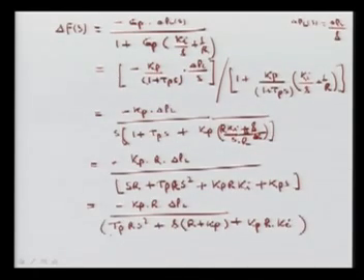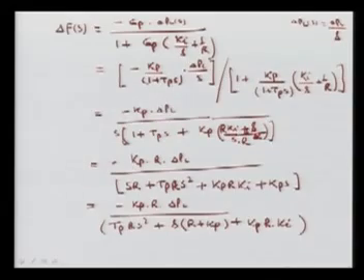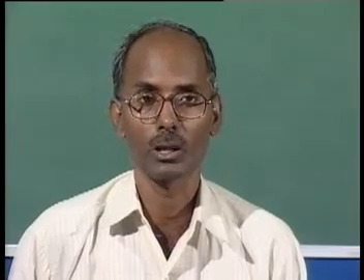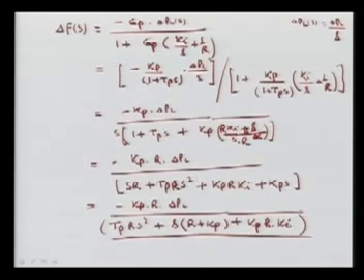Now we can see this denominator is a quadratic equation, means we will have the two roots, and the roots will be, if your Tp and T are fixed, that is basically related with the already designed parameter, because your governors once they are set it is constant, but the Ki, that is the integral gain, that we can change, we can set for our system performance. So this characteristic root is very, very important to decide whether your system is stable or not. First criteria that we have to meet, that it must show that we are having the stable closed loop, means this loop is stable.